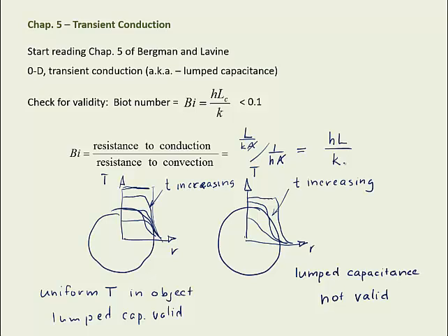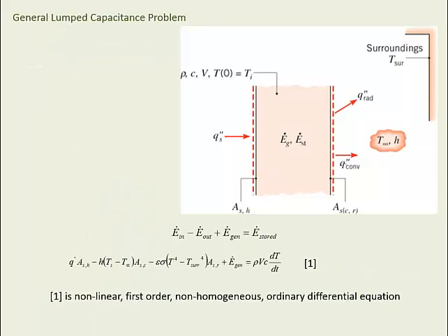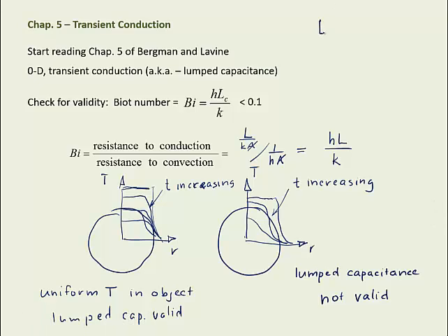The characteristic length, the general definition, if we get away from something, you will see plane walls and cylinders over and over, so you get used to what the characteristic length is. But if you have some other object, the general definition is that it's the volume over surface area. And if I think about a plane wall, and that's my center line, a lot of times we make the thickness of the wall 2L, so that half of the thickness is L.